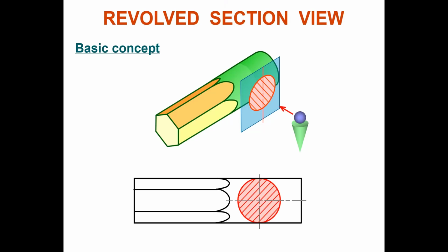Only one view. Because if you have a typical part like this and you make a side view, does that side view really help you to describe this thing? Let's say you make a plan view. The plan view also gives the same representation of this front view, right? This is the front view, the one showing only the front view. Let's say you make a left view. What do you see in your left view?